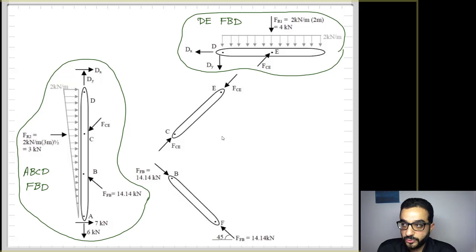It's hinged on both ends, no loads in the middle, so I can represent the reactions at the hinge ends as two equal collinear reactions, which I call here FCE. So now FCE is applied, and I'm assuming here it's compressing member CE. So these two forces are compressing it this way. So when I assume it to be compressing CE, then at joint E on member DE I need to show there FCE, the same FCE that I showed in member CE, but FCE here is reversed in direction when I apply it at point E on member DE, right?